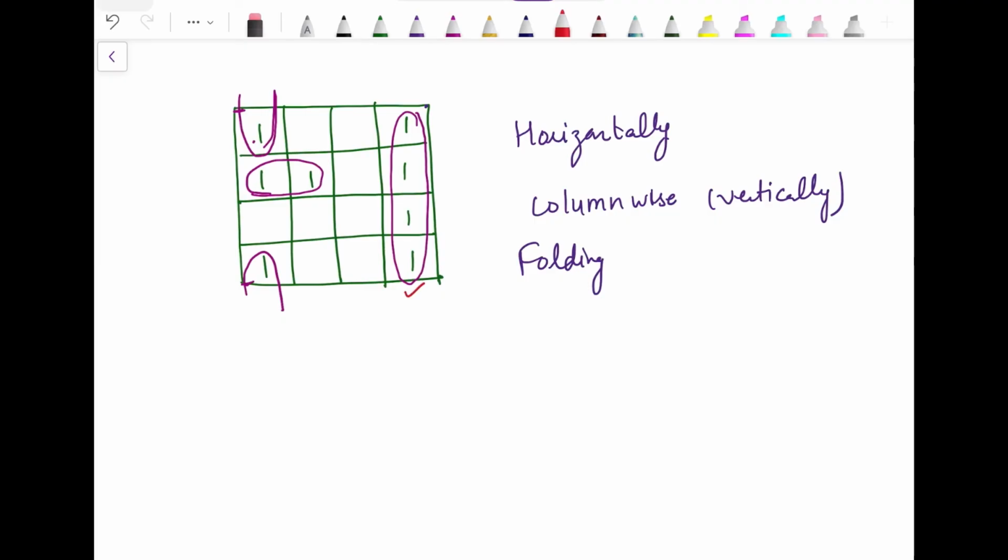Here we have a quad, this is a pair and this one is a pair. If someone is thinking we can also make this pair, there is no need of this pair since both the ones are already covered in the different pairs. So if you make this one, this is a redundant term which is not correct. These are the things we need to keep in mind.